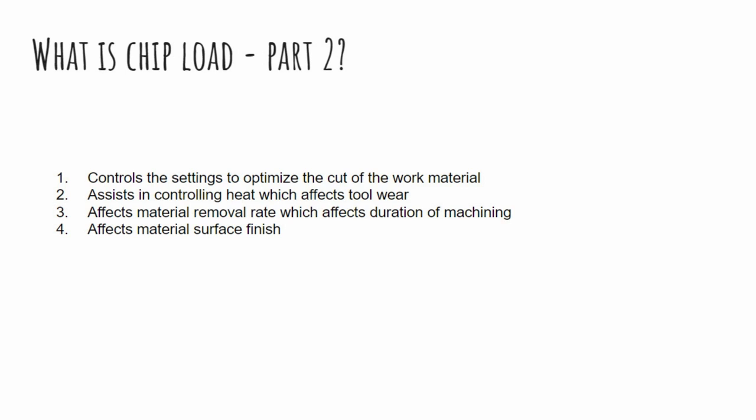So the reason we do that is that we get a better finish for the material and we keep our bits alive longer. So when we properly calculate the chip load, we control the amount of heat, which is the worst enemy possible to our router bits. Okay. So ironically speaking, running slower with a higher RPM, or even a slower RPM, is not necessarily going to keep our router bit cooler.